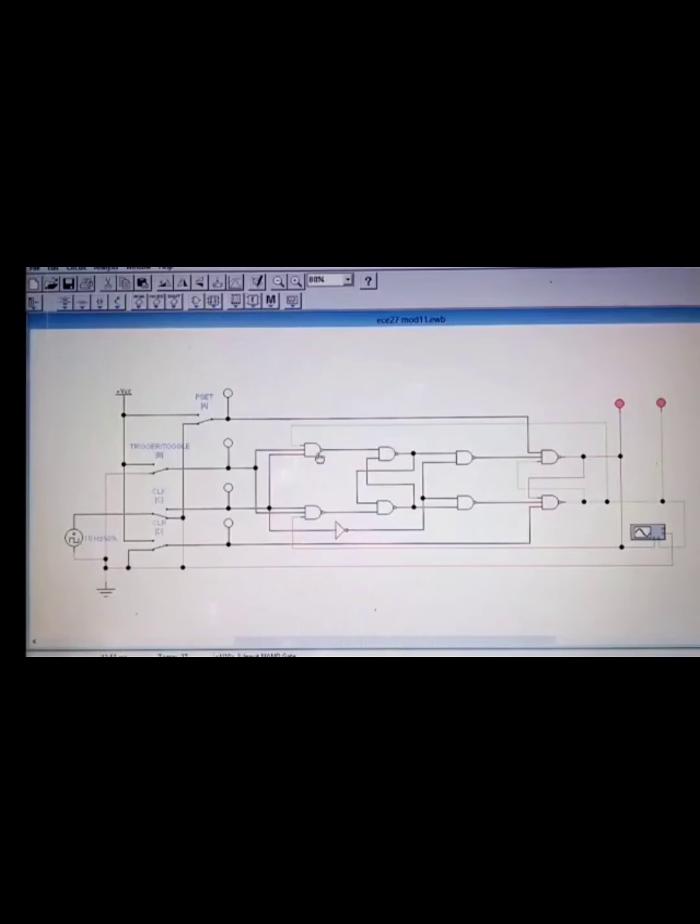So this is our logic equivalent circuit of the T flip-flop. As you can see in the circuit, it is made up of 8 NAND gates, wherein we have 4 3-input NAND gates and 4 2-input NAND gates. It is derived from the JK flip-flop equivalent circuit, specifically the master-slave JK flip-flop, where we added the preset and the clear. If we simulate the circuit and let the preset and the clear on, it provides a blinking output of Q and Q prime. So it means that the clock operation takes place.